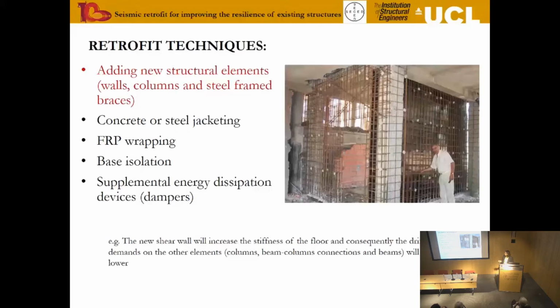One of these approaches is, for example, to add a shear wall or an additional wall to strengthen a particularly weak or low stiffness floor. However, such a method is actually quite disruptive to common activity, is expensive, changes completely the global response of the structure, and often requires also intervention at the foundation level in order to carry the additional shears, etc.